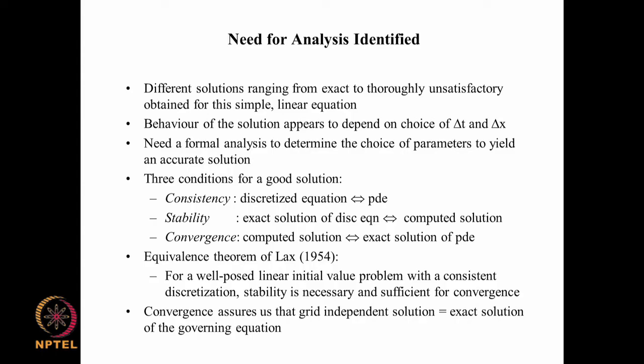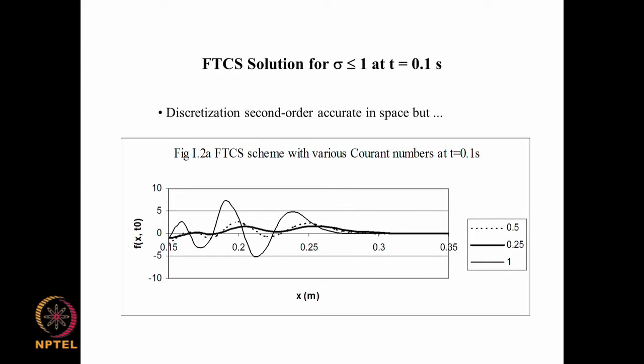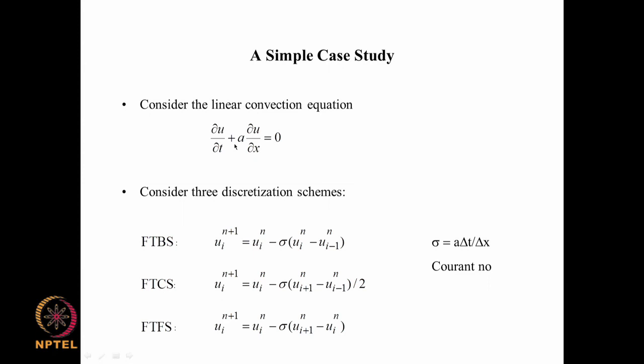So this is bad because if it is something to do with the equations we can blame the modeler, or the mathematician, but these delta t and delta x are the choices that we have to make in order to get a numerical solution, okay. So now the blame is on us, we have to find the correct values of delta x and delta t in order to get a solution, and we see that sometimes it is coming okay, very rarely, but most of the time it is not coming okay, even for the simplest case using approximations that apparently have no problem with them, okay.